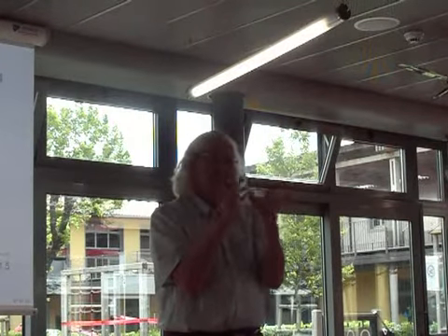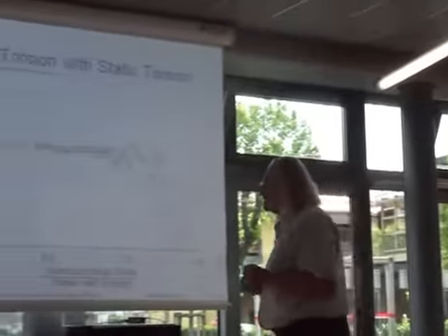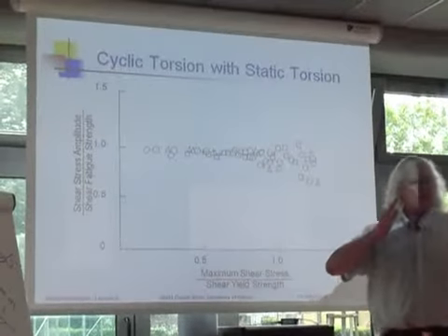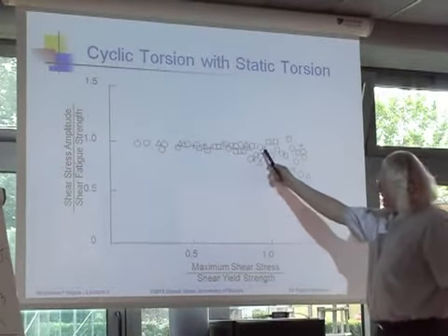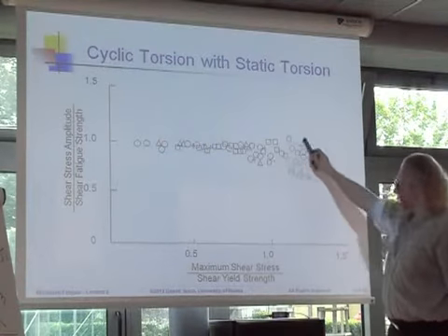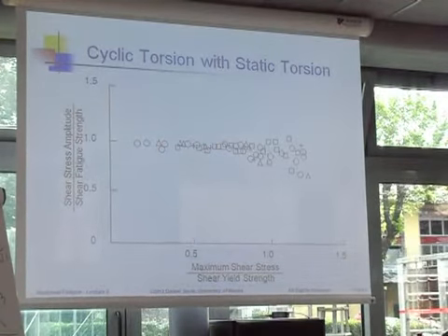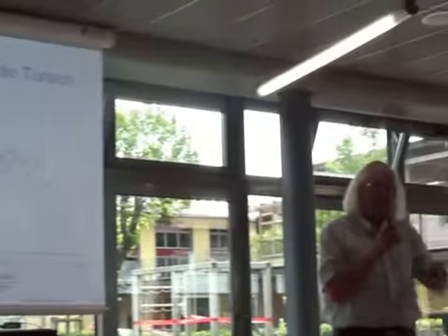But what is the difference physically between a positive shear and a negative shear? Direction. Yeah, only direction. Otherwise, there's no difference. Only direction: twist clockwise, counterclockwise. So we expect no change between positive and negative, but even if we took the absolute value of the shear stress, you can see absolutely no effect until you get above the yield point. So we might conclude that there is no effect of a mean shear stress on fatigue from this data.